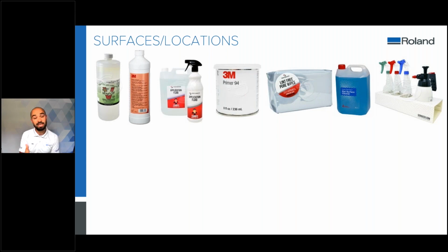There are some application fluids and things like that that you can use if you are going on to trickier materials, or if you're not very comfortable with applying large graphics. By and large, if possible, you want to apply your graphics without any sort of liquid behind them, because the liquid will reduce the adhesive strength when you initially put it on.